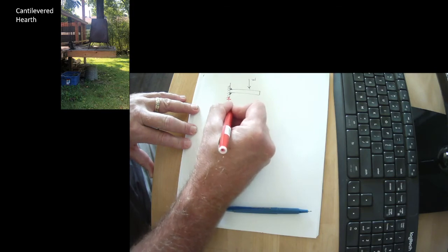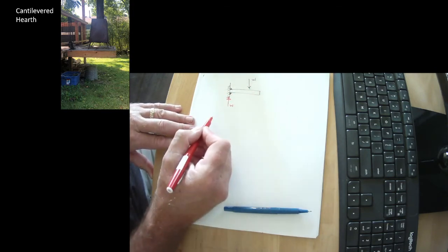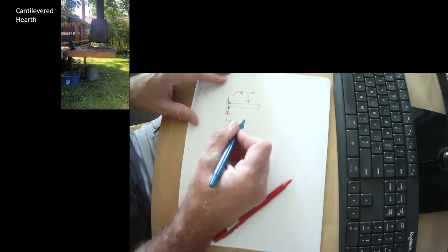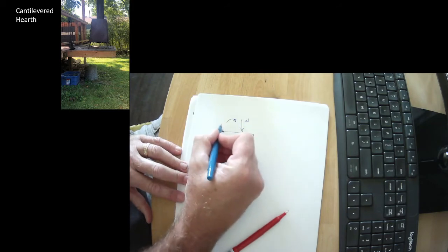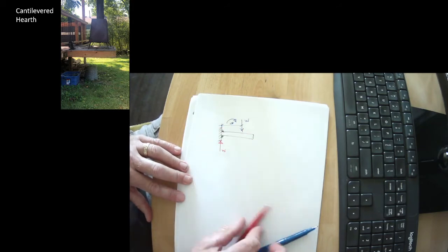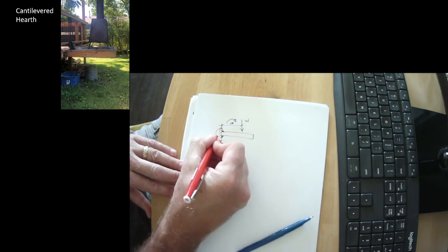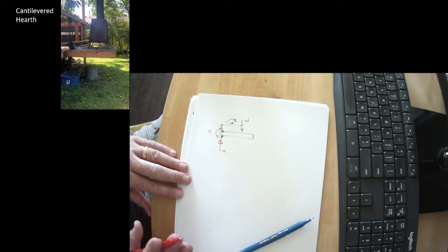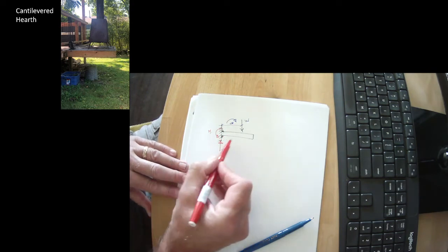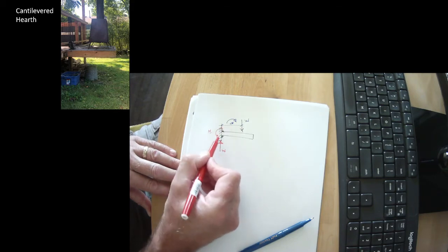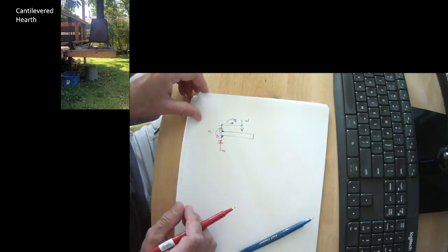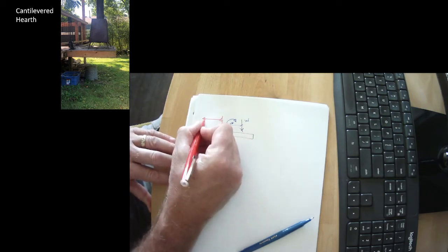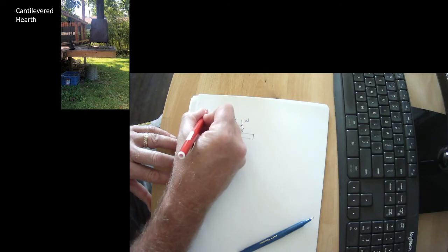The vertical load has to get resisted here because we have nothing back in there. So what resists the overturning? Due to this eccentricity, there has to be a moment. So that is just a very simple cantilever problem. We have weight, we have resistance, and we have a moment that resists the eccentricity. And what happens back here is somebody else's business problem.